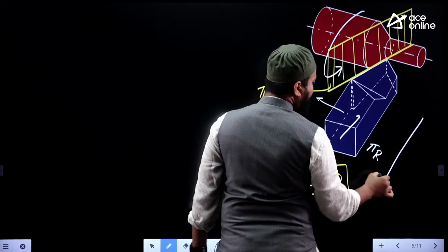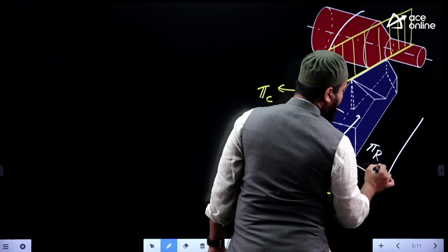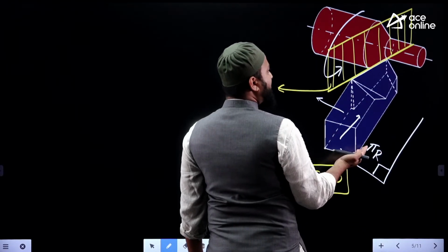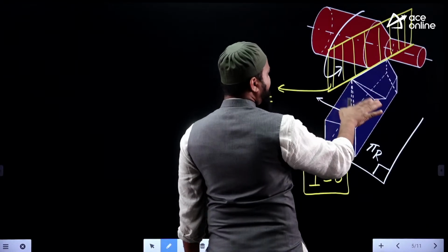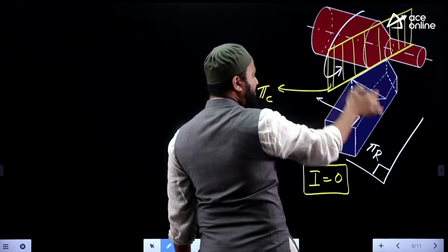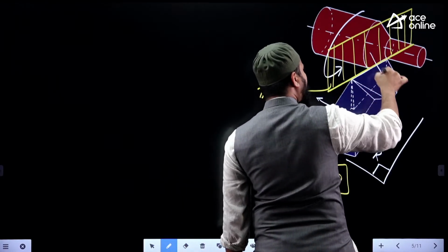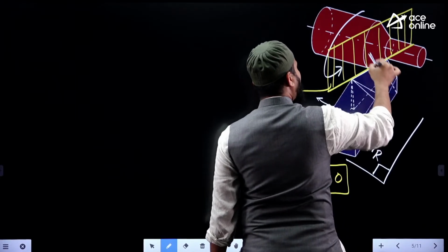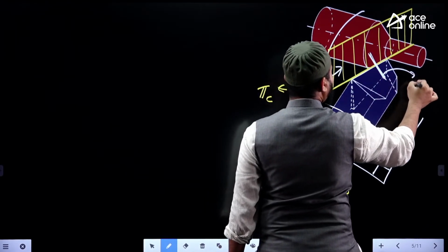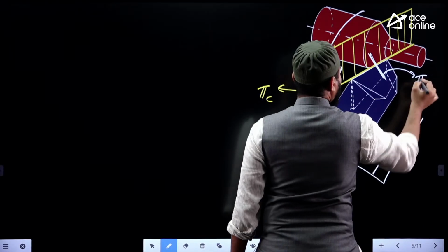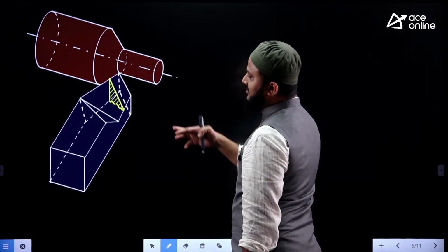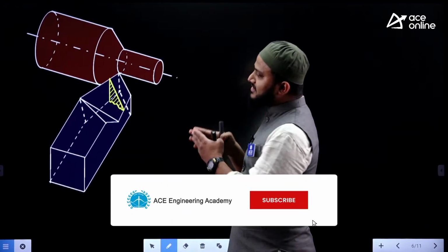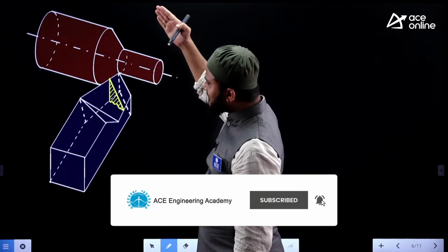One plane we have is parallel to the base, on the entire tool and workpiece projection we made, that's the top view. And there is the cutting plane, which is perpendicular, and I am taking one more plane which is perpendicular to both these planes. We call that one the orthogonal plane. So based on that plane, if I look at only the tool, the wedge shape inside the tool is what we notice on the orthogonal plane.